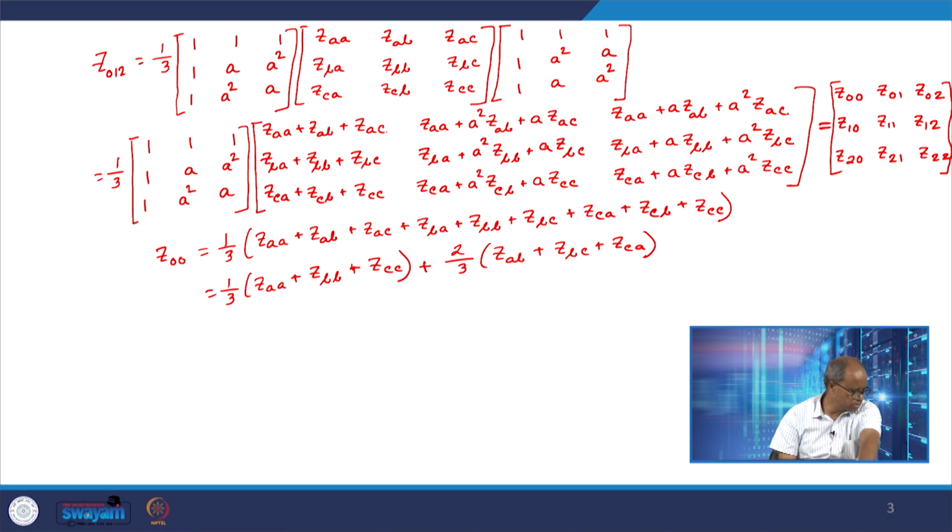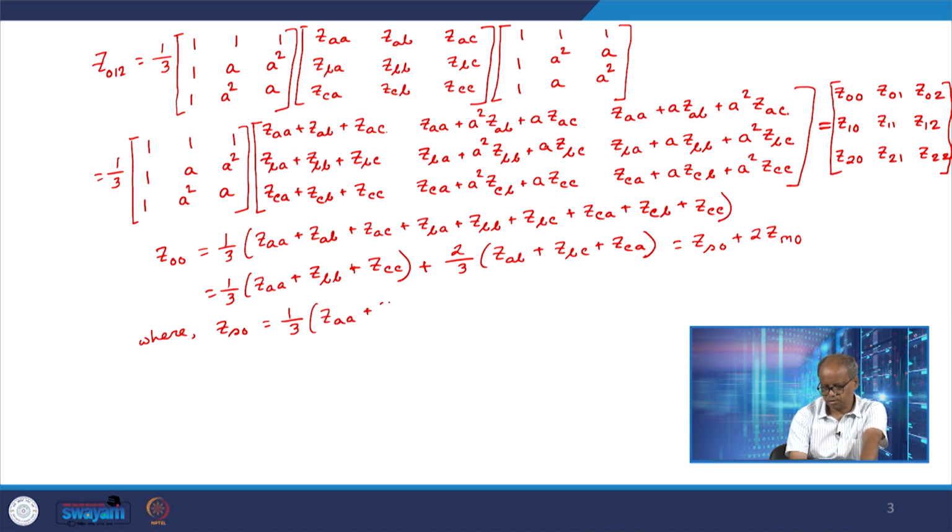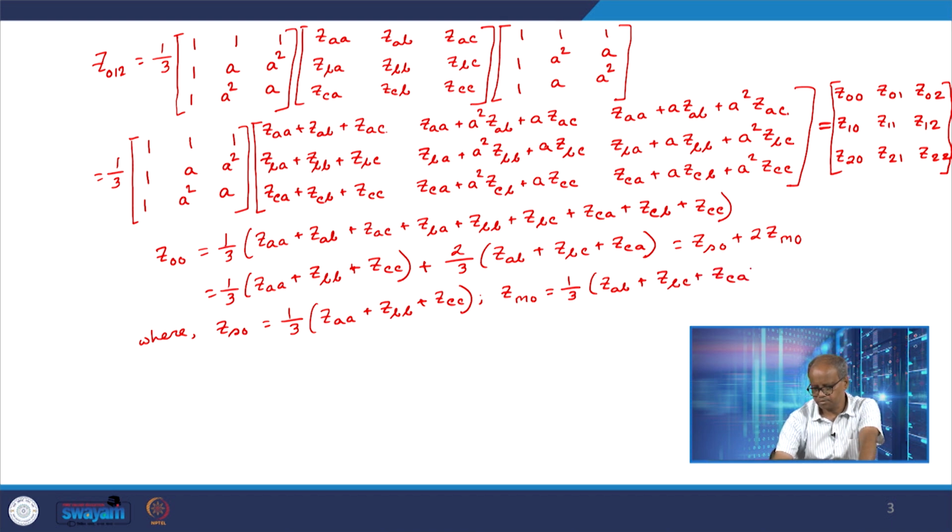So we call it ZS0 plus 2 ZM0, where ZS0 is 1 by 3 into ZAA plus ZBB plus ZCC, and ZM0 is 1 by 3 into ZAB plus ZBC plus ZCA.